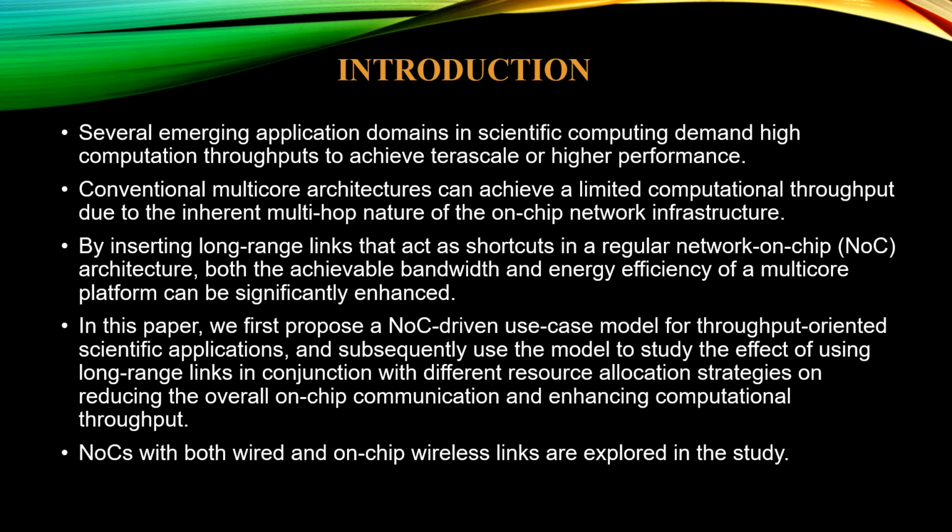To achieve this, they have proposed to insert long-range links which act as shortcuts in regular NOC architecture. The on-chip network is built using both wired links as well as wireless links. Wireless links are used as long-range shortcuts to reduce inter-core latency.